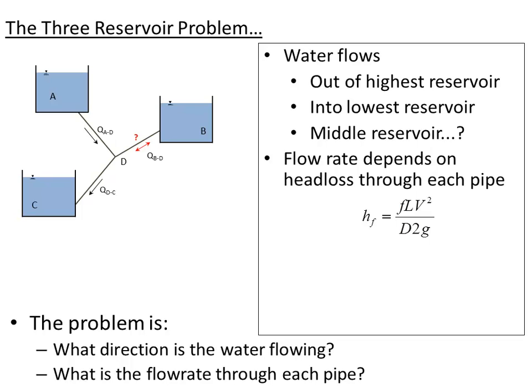And so what can we say about the head or the energy at D in terms of how much energy there is at the reservoir C? More or less? Why do you say there's more? The elevation's higher and flowing that way. Okay. Even if the elevation wasn't higher, it still could be more energy, because remember that the hydraulic grade line is independent of physical location. So what really is the defining, like why the energy at D is greater is just by definition, water flows from high energy to low energy.